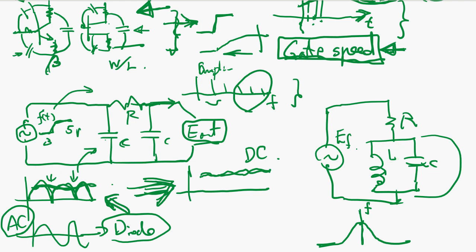So if you have a coil, you attach it and run this frequency analyzer, and they have a frequency analyzer. It does Fourier transform for you and shows the frequency domain characteristic. And if you run the frequency analyzer, it shows the peak frequency. From this frequency, you can calculate L. Okay? So that's a frequency domain analysis. We're going to do more detail in the following videos.